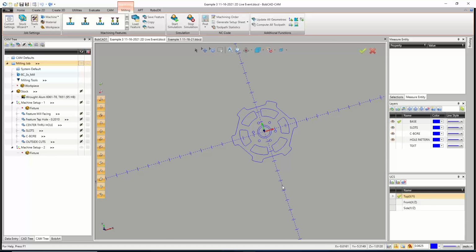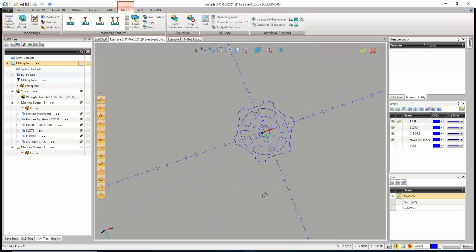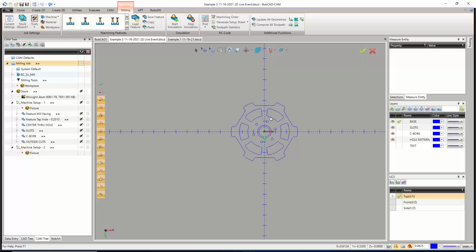For us right now, we're just going to grab it. I'm going to go over the x-axis, so I'm going to flip it this way. All right. Or if we go Control, there's a bottom view on here. How does the bottom view do it? So yes, we could basically just go to a bottom view, and that's going to be exactly what we want. So it's just click that drop down and then that button right there, or it's Control 4. So Control and the number 4 above your keyboard will give you that bottom view.